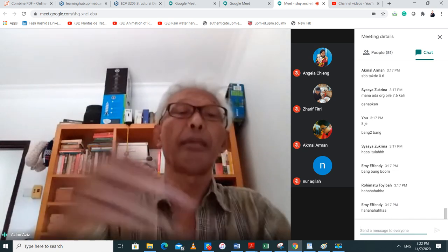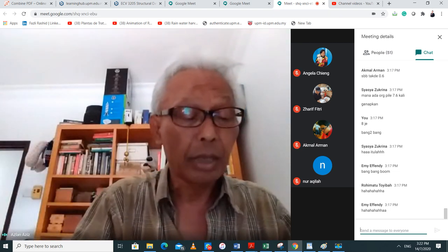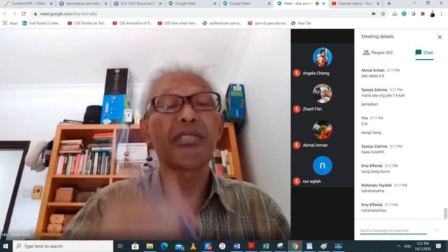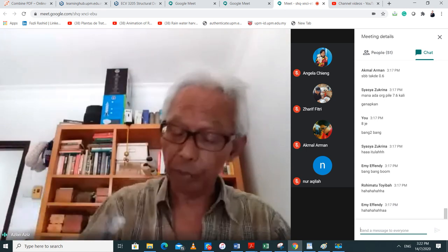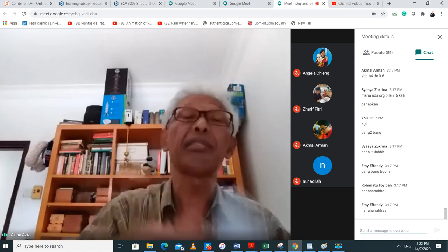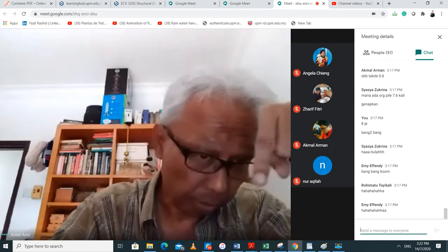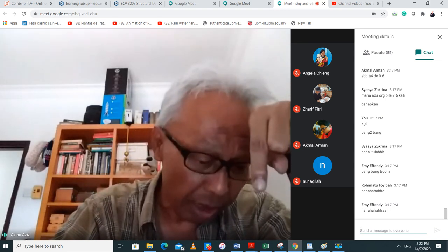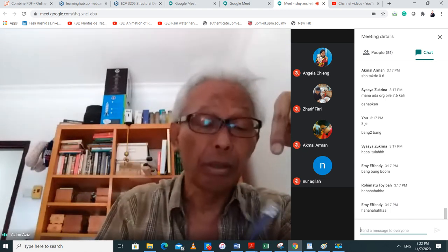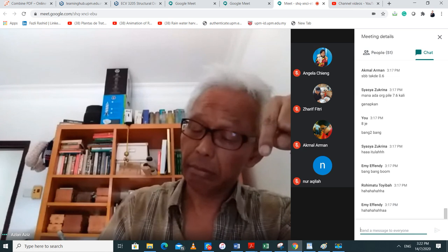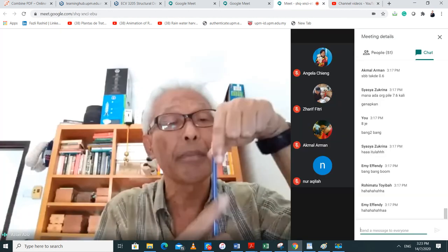1625 kilonewton of ultimate compressive load. But at that point in time, at 9 meters, you notice that ASFS, the skin friction, is only 421. But I have an uplift load, which is 563. So 421 is in this direction, going downwards. But the uplift load of 563 is in this direction. Uplift is pushing my pile out.